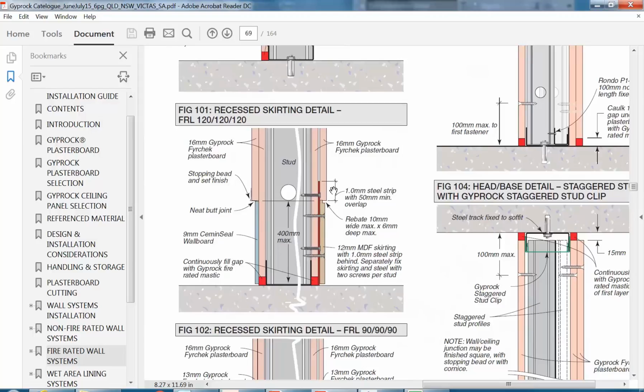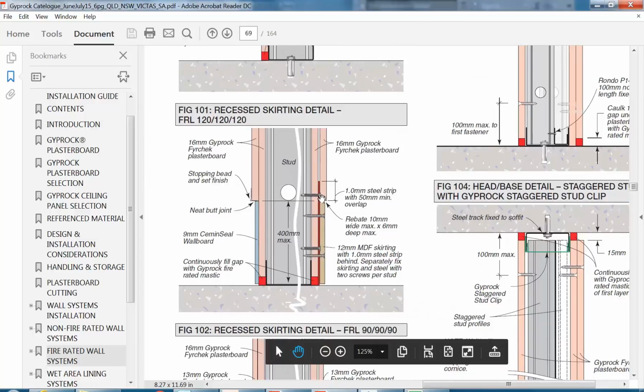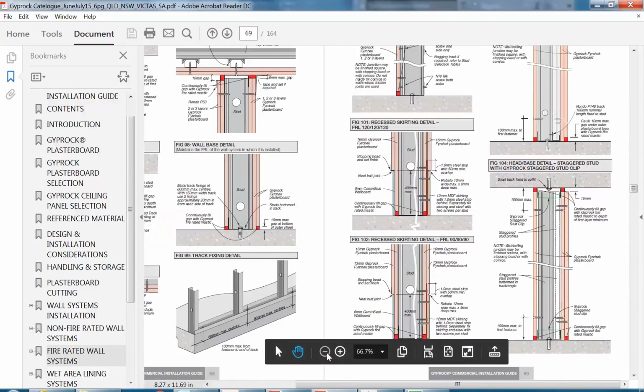If you're doing a design for families, if you know it's going to be that sort of dwelling, that's probably a more appropriate detail, because kids and people who aren't as careful are going to damage the walls otherwise, and so that's really the purpose of the skirting there. It protects the wall because it's MDF instead of plasterboard, and I have seen people go through plasterboard several times. I'm sure everyone has. If you fall into a wall like that, they're not the strongest.